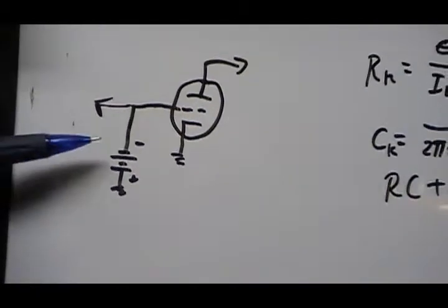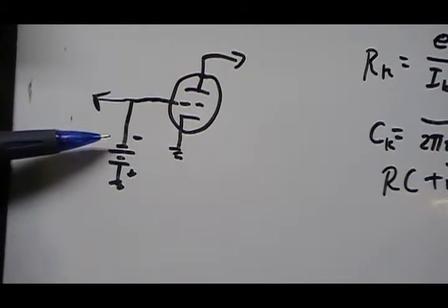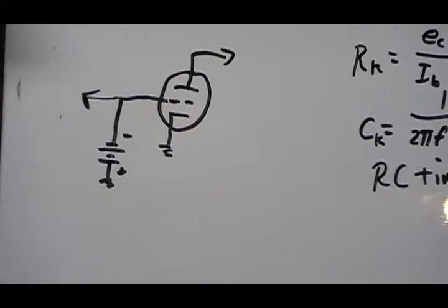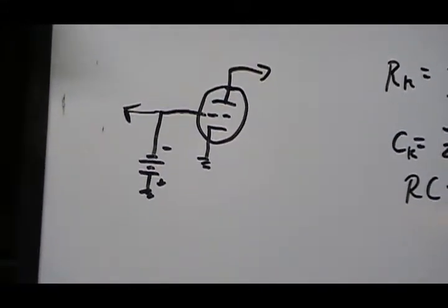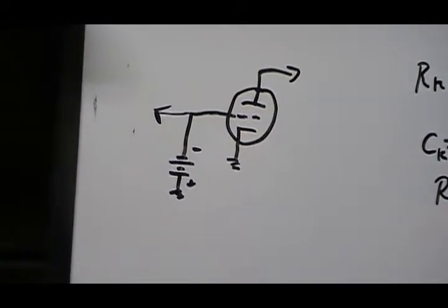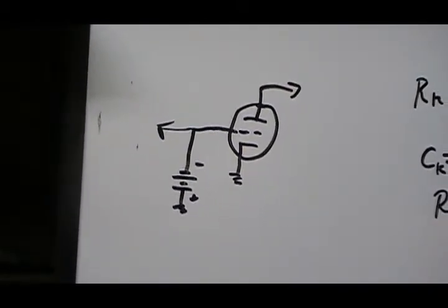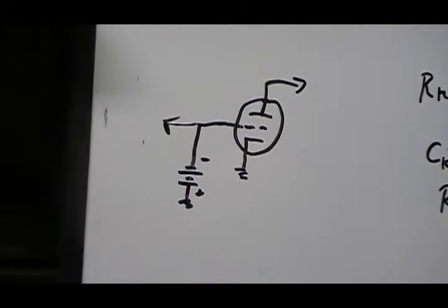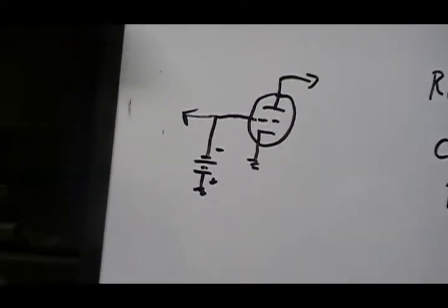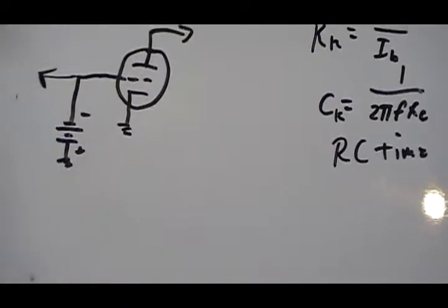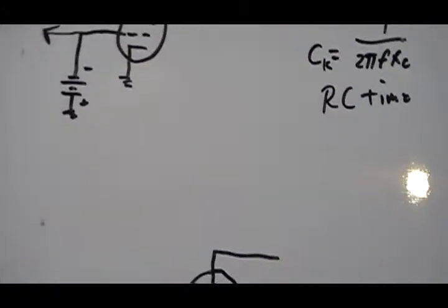So they would actually be just fine being hooked in there. If you're getting like 7.7 volts or something with a digital voltmeter, try them. They'll probably work just fine for you. If not, you can put a resistor in here, and we'll get to that in a minute.